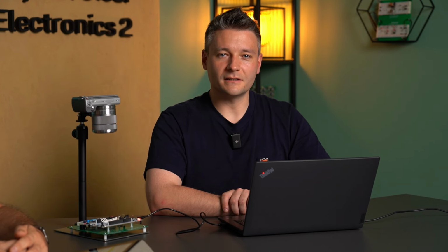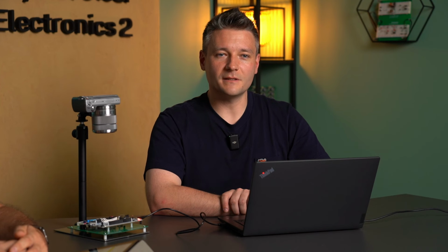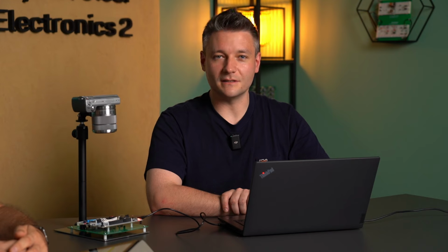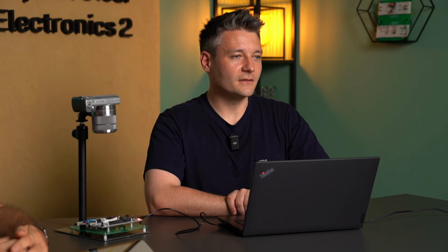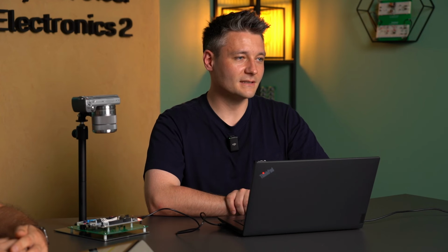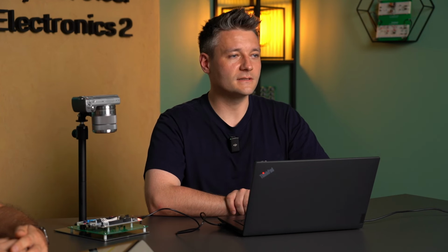Accuracy is also important for quartz crystals, which are measured in ppm/Celsius degree, where ppm stands for parts per million. 1 ppm per Celsius degree means that the temperature change of 1 Celsius degree will cause the frequency to change by 1 part per million compared to the reference temperature of 25 Celsius degree. For more information on the crystals and their wiring, see Chapter 5.3.8 of the microcontroller datasheet and the AN2867 application guide.